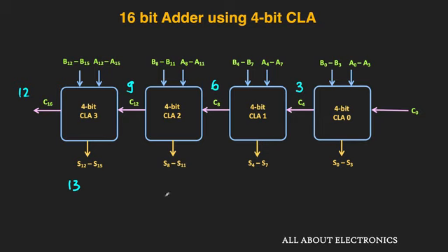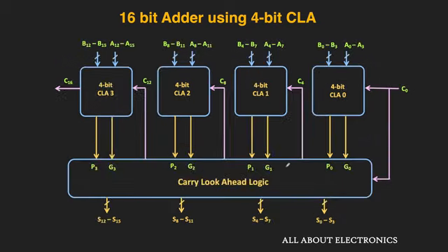But in this design, each block has to wait for the incoming carry from the previous stage. So if you want to further increase the speed of the addition, and if we can afford a little more complexity and cost of the design, then this is another design. Here once again, the 4-bit CLA blocks are used. But here, the carry for each block is generated using carry look-ahead logic. So basically, here the carry look-ahead logic is implemented in 2 stages.